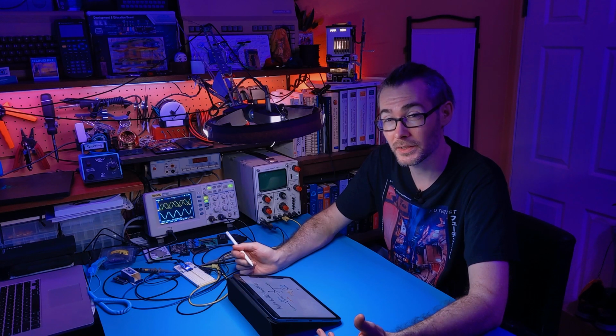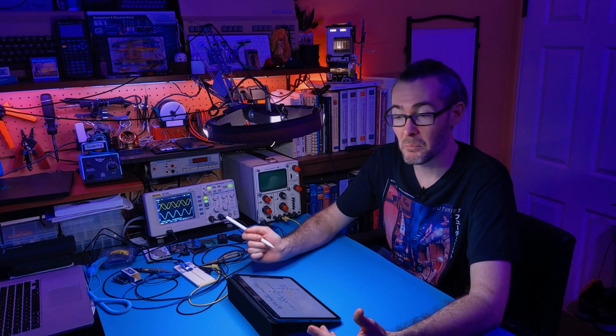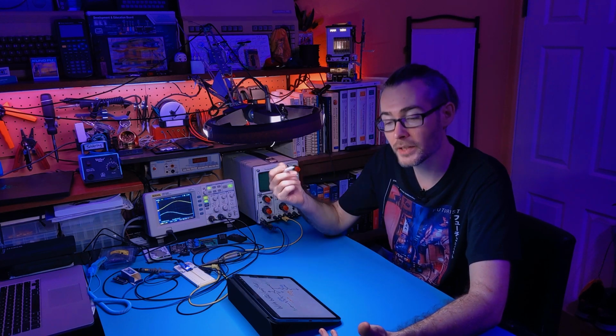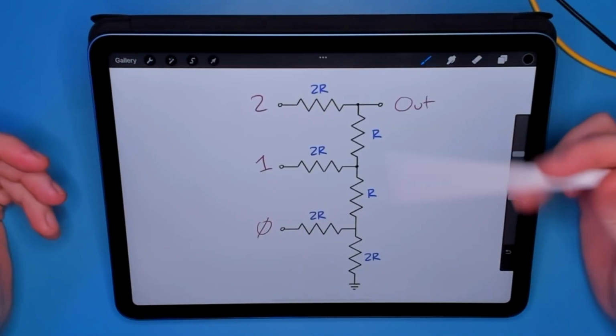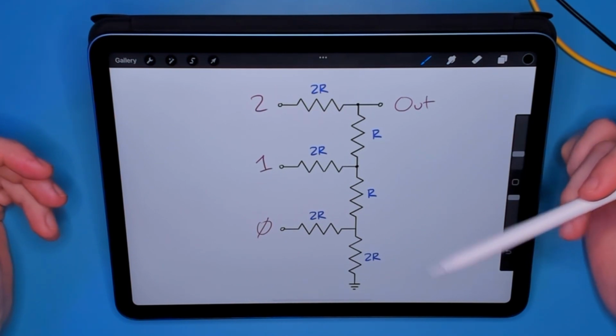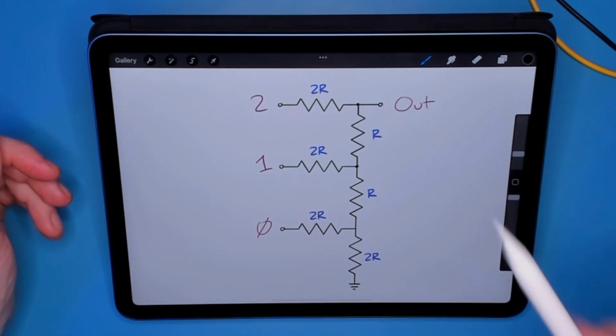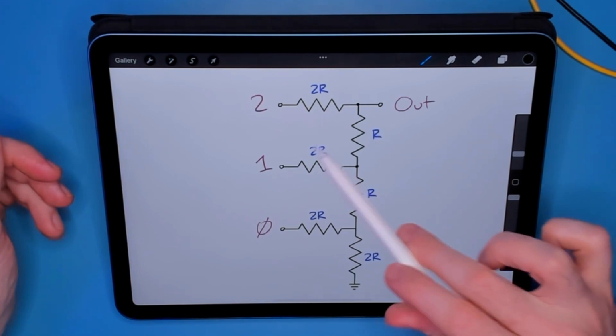While in theory, a binary weighted DAC should be simple, there's kind of a big problem. The power of 2 series that the resistors are chosen from maps really poorly to the power of 10 E series that parts like resistors are manufactured to. And consequently, if you take a given resistor and you double the value a few times, you'll quickly end up with a value that's either hard to find or maybe doesn't even exist. For this reason, it's far more common to build a DAC using an R2R resistor ladder, which uses twice as many resistors, but only the same 2 values R and 2R.